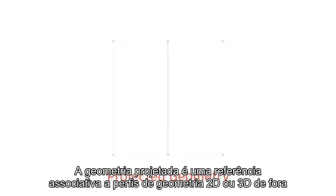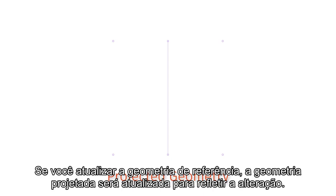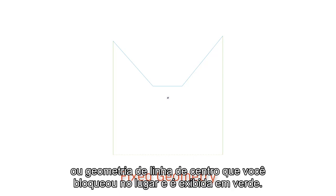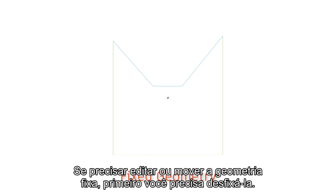Projected geometry is an associative reference to profiles of 2D or 3D geometry from outside the sketch that are projected onto the sketch plane and display as purple lines and points. If you update the reference geometry, the projected geometry updates to reflect the change. Fixed geometry is any sketch, construction, or centerline geometry that you have locked in place and displays as green. If you need to edit or move fixed geometry, you first need to unfix it.